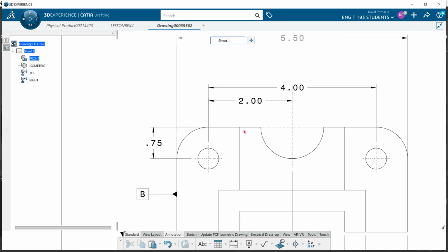That way on both of them you're dimensioning from this center to here. I'm trying to make these holes and pins all line up with each other. That's why I'm so focused on dimensioning these three dimensions. Those are what's going to control how they link up to each other from one part to the next. These are the things you've got to think about.